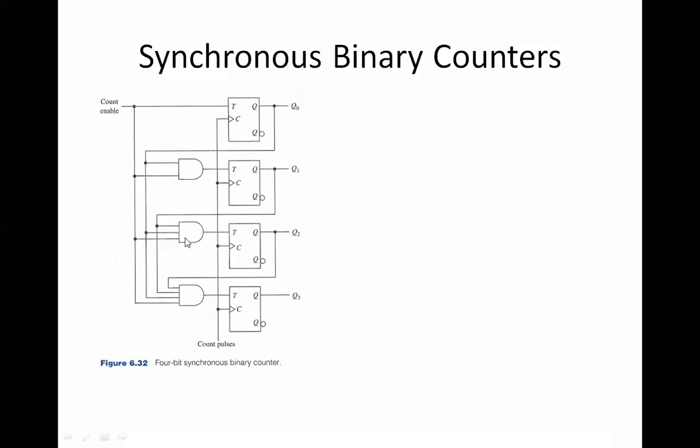Now in the next one, what is happening? It should take this and also take this, and also check what was the value previously in Q naught. So as your number of stages increases, your number of inputs to the AND gate increases.